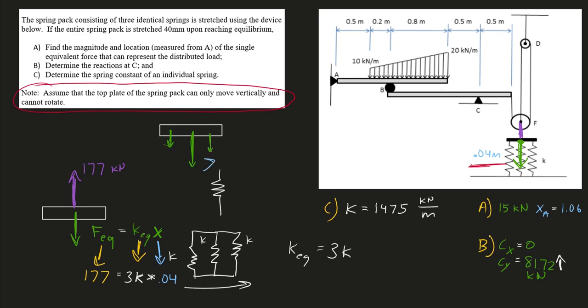But like he's saying, we're not worrying about this. But also it doesn't really matter because since each one of these springs here is identical, that means their forces are going to be the same because of course they're going to have the same stretch by virtue of them being in parallel. So for this specific problem, because these springs are identical, this note is kind of redundant here. So just wanted to explain that.